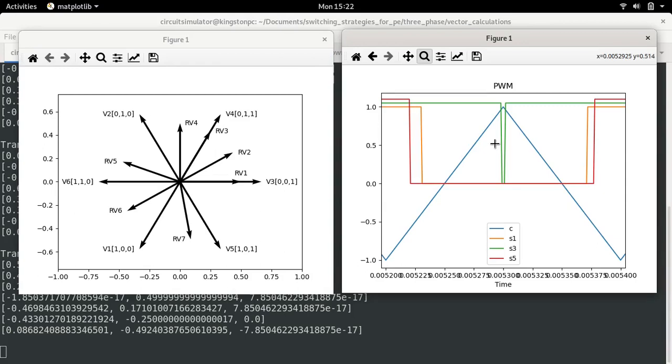Because remember, even though we are getting something similar using sine triangle PWM, the disadvantage of sine triangle PWM is that as your current rating increases, as your voltage rating increases, you may not be able to guarantee the maximum. That is, you can't always guarantee that things will be like this, because remember, your modulation signal is coming from a control output, and if it is coming from a control output, there can always be displacements, right?